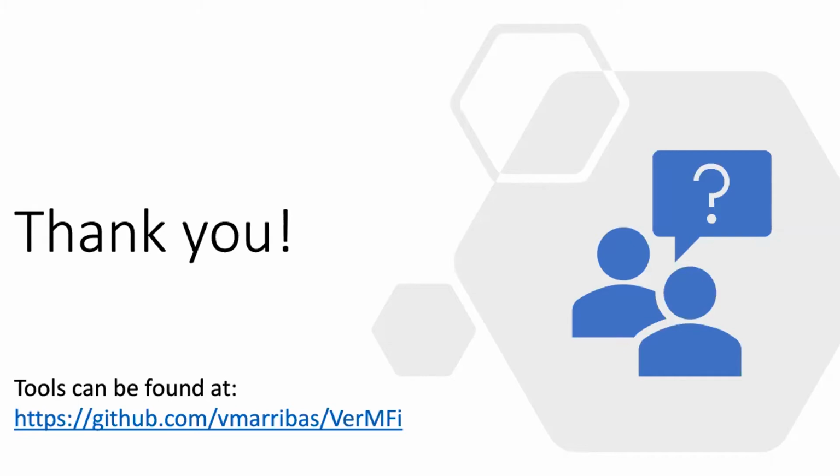David, is there anything you want to add? No, I think Silver is basically for side channel analysis and for verifying different masking schemes. As I already said, it supports a wide variety of security notions. We check basically every established security notion, and also composability. So this tool is quite generic, but not for fault analysis or fault injection analysis. It can only be used for masking and side channel resistance at the moment. For example, I didn't see a multiplicative masking or additive masking example in the presentation, but because the notions are generic, it can also be used. Yeah, sure. That's the main goal.